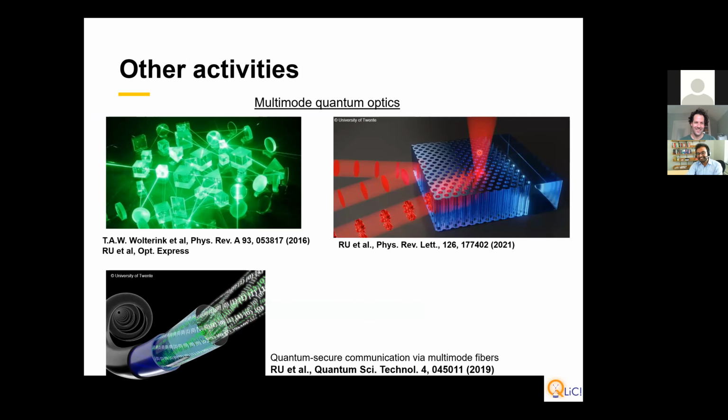So this is one way, right? This is work from earlier this year with COPS, where we engineer the wavefront. You control the phase of the light that's coming onto the photonic crystal. Here I was using an external spatial light modulator to do that. But a photonic solution would be using a metasurface to engineer the phase locally, so that you can destructively control the scattering, or at least reach a phase where you can interfere the two better and reject the laser.